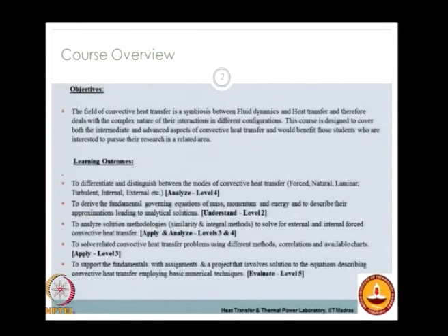So you could look at things like forced convection or buoyancy driven convection, which is called natural convection or free convection. Then depending on whether the Reynolds number is less than a critical Reynolds number, you can look at flows which are laminar, or flows which become unstable and transition and finally become turbulent, and depending on the flow configuration, whether they are internal or external boundary layers.